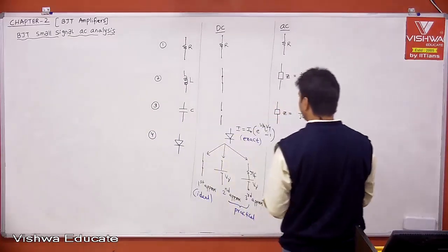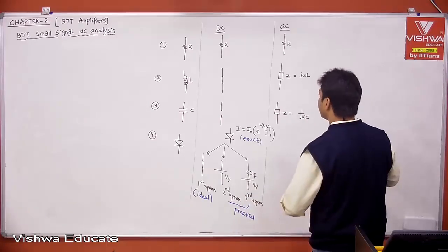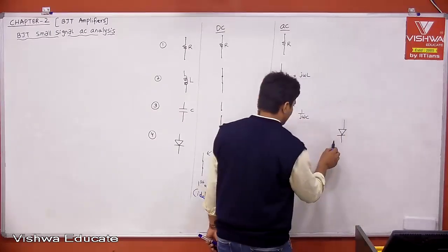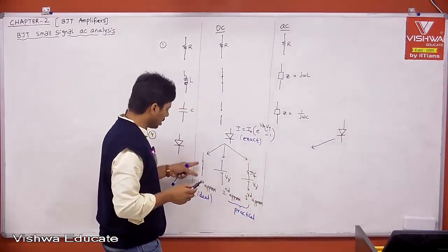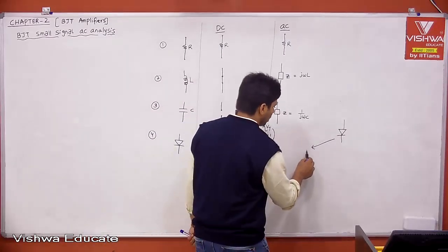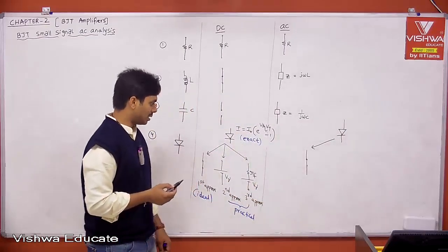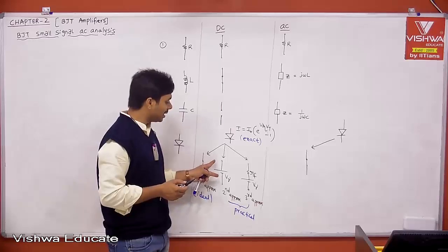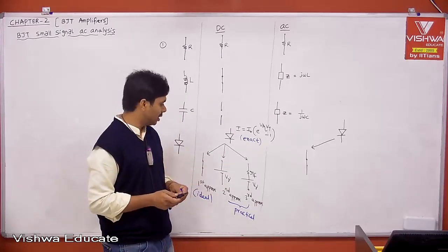Now if you ask me about the case of AC analysis, actually I don't have space here, let me expand here, you try to manage. Okay, this is your PN junction diode. Now coming to your first approximation, there is nothing, whether it is DC or AC, it is short only. Okay, under AC analysis, then what about this? We have to replace it with its AC resistance or dynamic resistance. That is what we need to have.